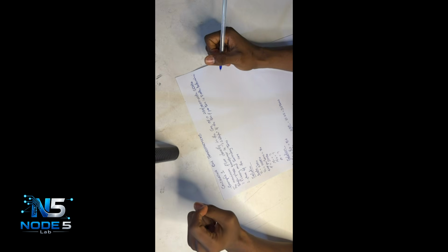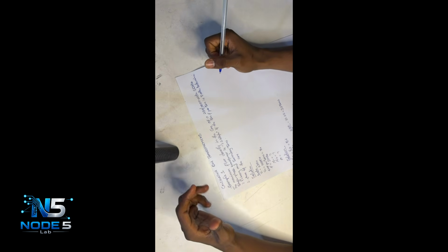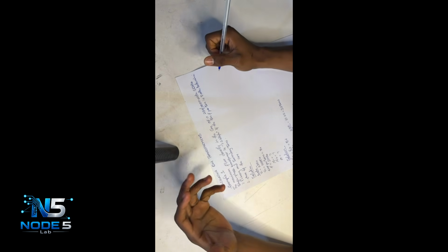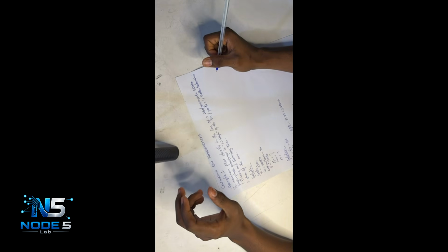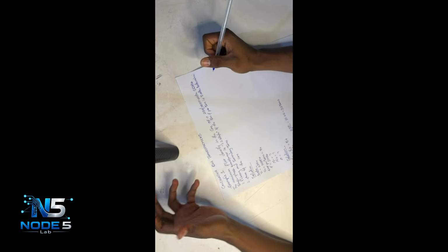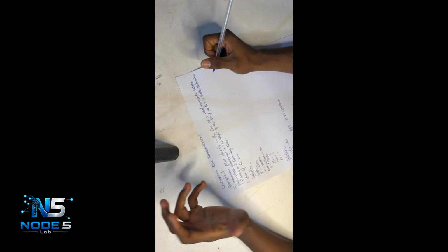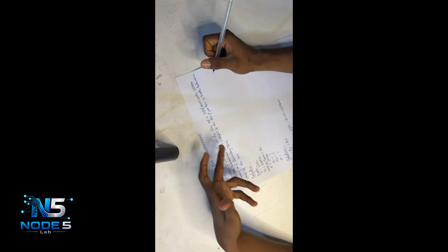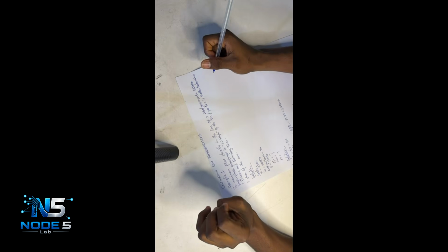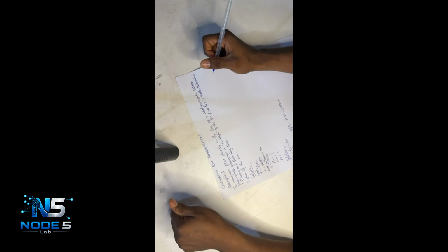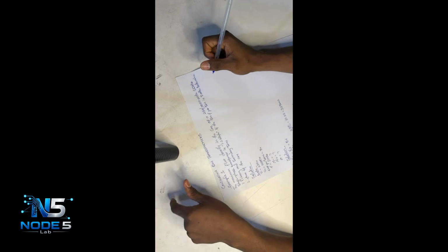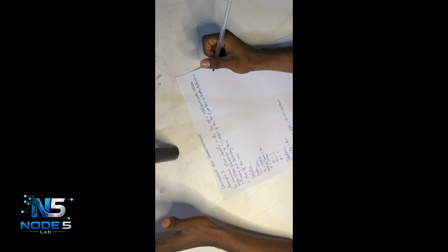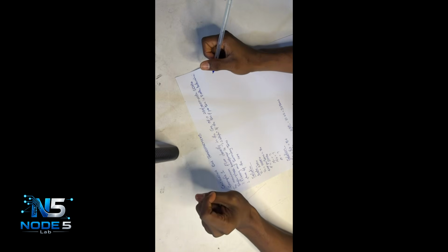So this is the question, and it's telling us that the maximum flux density in the core of a 250/3000 volt 50 Hz single phase transformer is 1.2 Webers per meter square. And then the EMF per turn is 8 volts. That means the EMF is the same in both windings, the primary windings and the secondary windings.